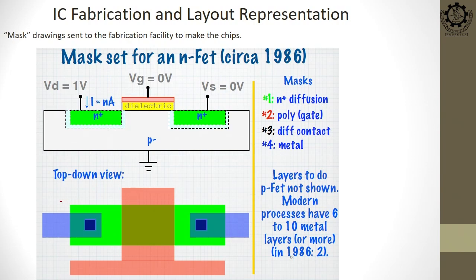So, what we discussed now is this extended version is the gate, this is our source and this is our drain. And what I told you is that there are some windows, and that window will tell you about the metal deposition, right. Different colors are used to help the designer view the different regions. Beneath the gate is your actual active region, the length is known as the active region, and this is your diffusion.